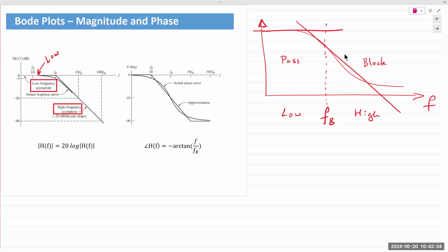Okay, so a Bode plot is technically a plot of the transfer function in decibels as a function of frequency plotted on the log scale. Both the axes, the y-axis and the x-axis, are compressed. This allows us to plot a very wide range of data points on a small chart. Okay, so again, this is something we'll talk about in detail, but I just wanted to give you this heads up so that you are able to answer the homework question. Okay.